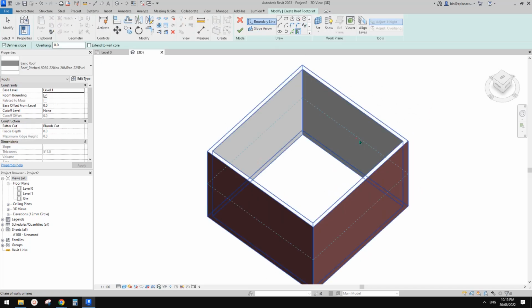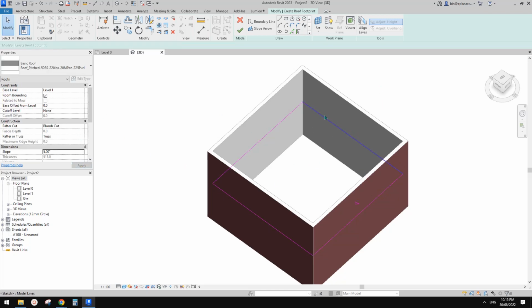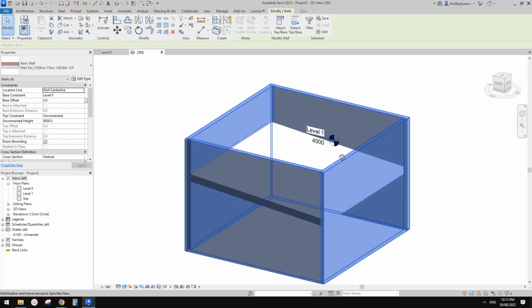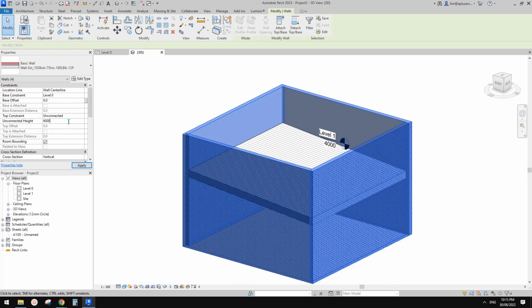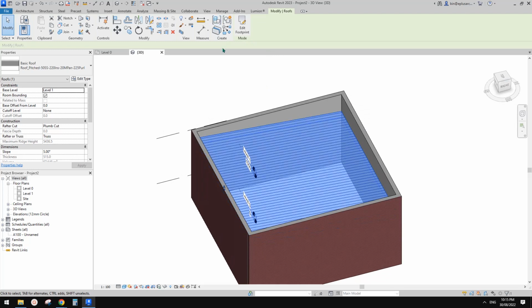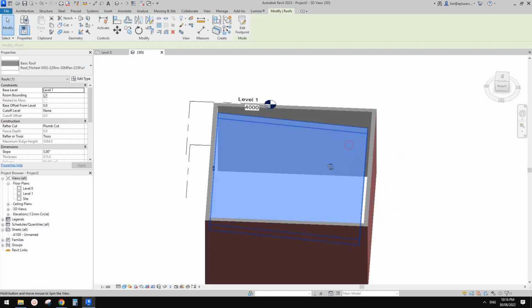So I'm going to use pick wall, and then maybe I'll just uncheck slope and make sure they are inside of this wall, and then maybe give it 5 degrees. So I want to have a roof inside this wall. Maybe I'll just lower this wall a little bit, I'll make them 6 meters high. Yep, all good. And then we need a box gutter here, so I'm going to edit footprint, give it, for example, 300 mil, and that's some space for the box gutter.